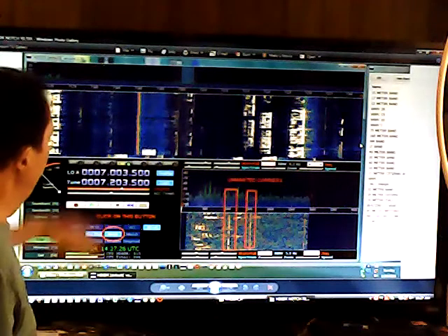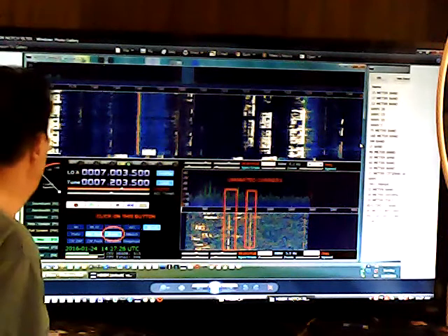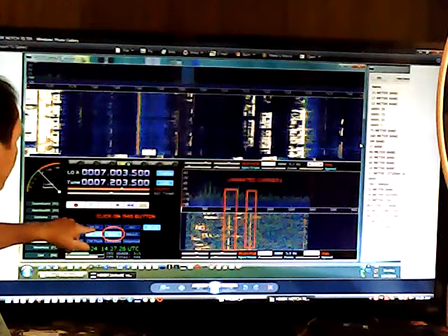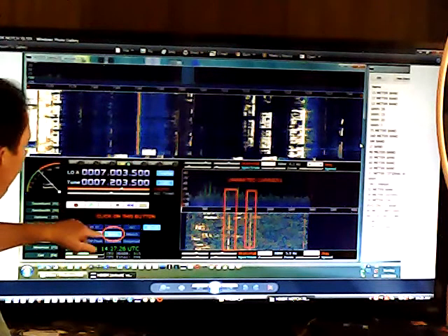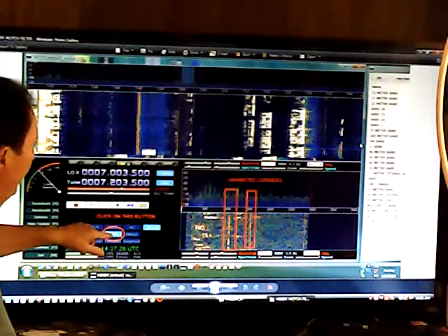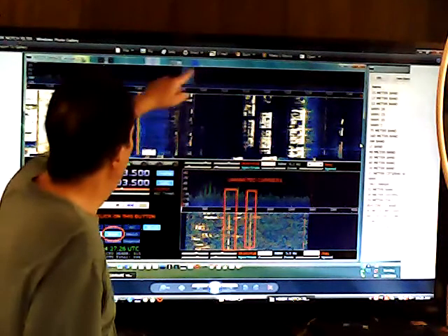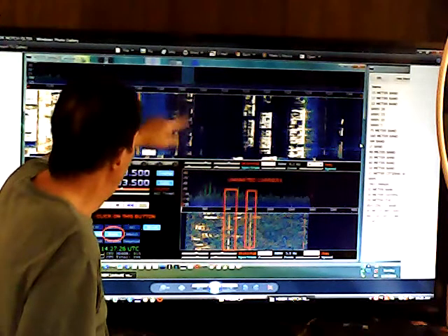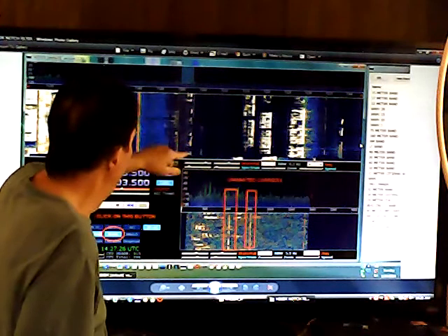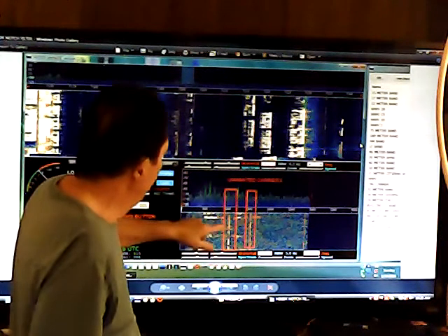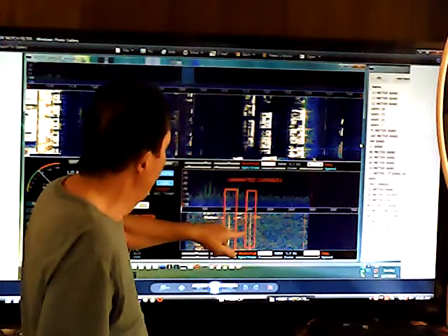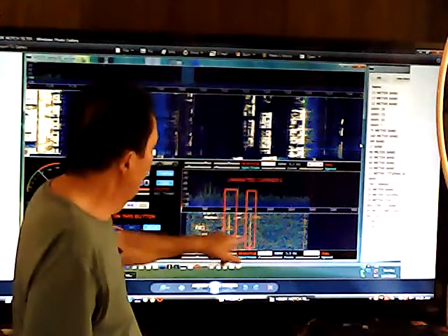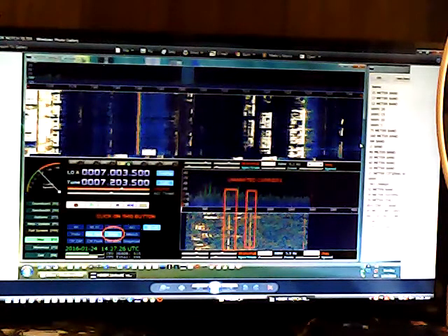Another advantage of the HDSDR software in using a SDR is that you have additional filtering capabilities. You have noise reduction, noise band filtering on RF, and a very important feature, which is the notch filters. Here is a signal that's selected, and you can see interfering carriers, some people tuning up, some other QRM in that signal. In the graphics display, it produces tone and noise, which you can get rid of with the notch filter. So I'll select these two noise bands and eliminate them.